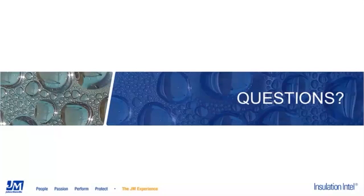Very, very complex, lots of stuff on it. JM has a couple of letters, general letters, and a tech data sheet on this subject to which I can refer you as well. But I'll say in general that insulations of all types get, I think, an inappropriate bad rap for causing corrosion under insulation, or CUI. What really is the source of the corrosion is water that gets into the insulation system.